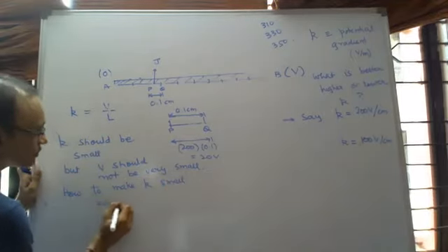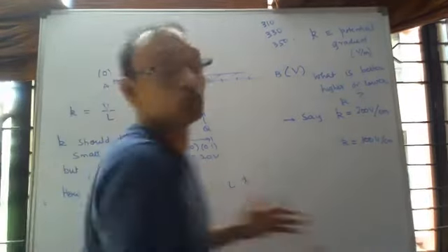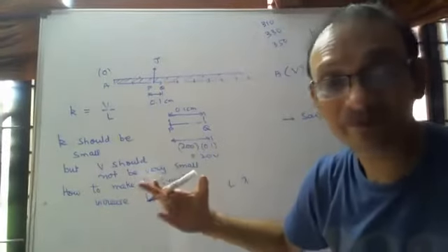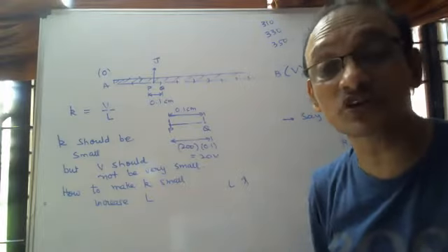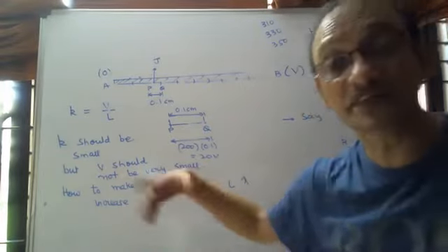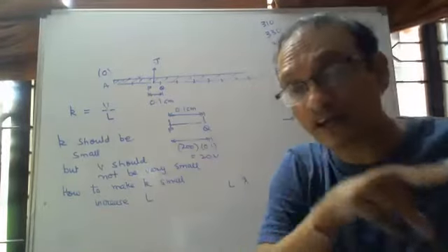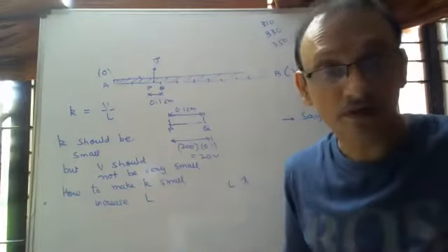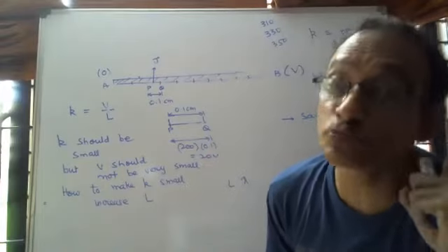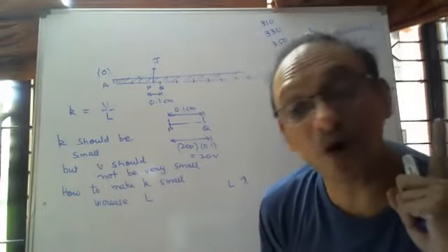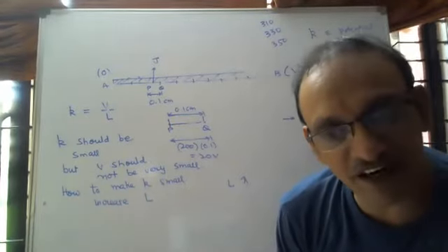Increase L. That's why they use the 10-meter wire. Yes, sir. It's a very long wire. 10 meters is huge, but you can't keep that 10 meters in one straight piece, you will have to fold it around. Right? So for a potentiometer with superior sensitivity, smaller potential gradients are better than higher potential gradients.